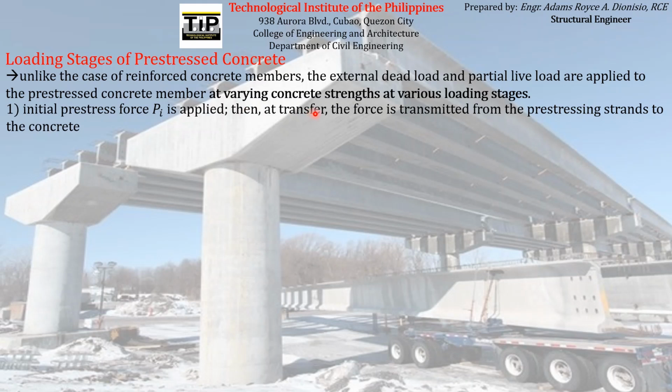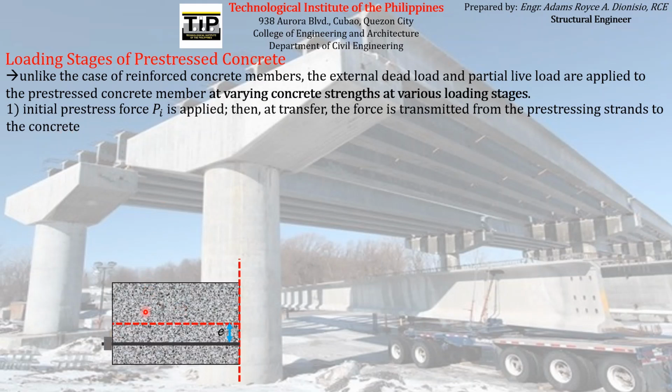Then, at transfer, the force is transmitted from the prestressing strands to the concrete element itself. If you can remember the stages of prestressing that we have studied from the previous meetings, after the hydraulic jack imparted a jacking force to the prestressing reinforcement, it will be cut after the concrete has attained enough strength to resist the compressive force that will later be transferred by the prestressing reinforcement.